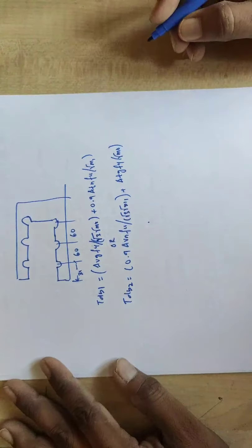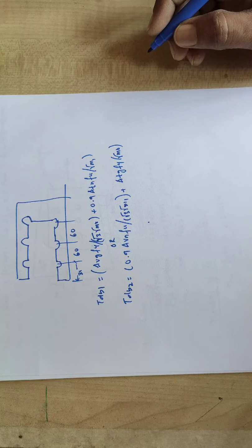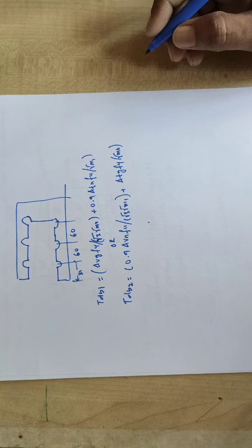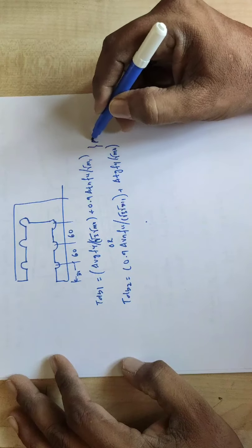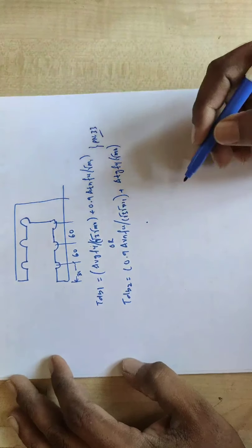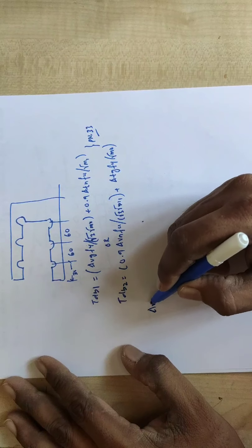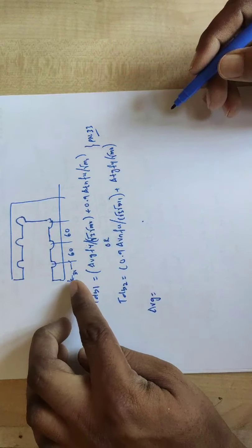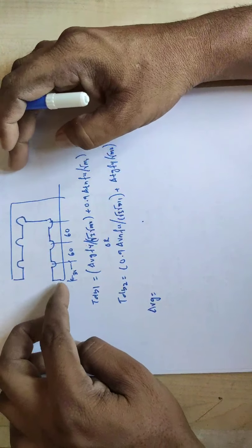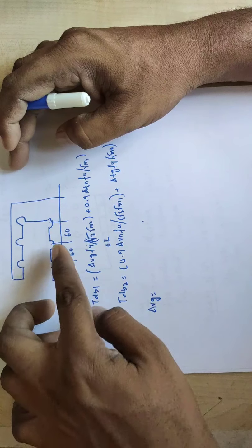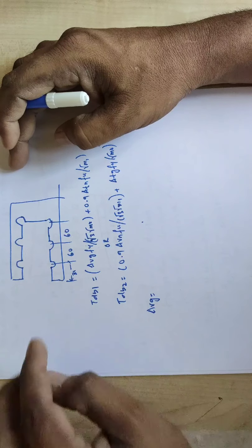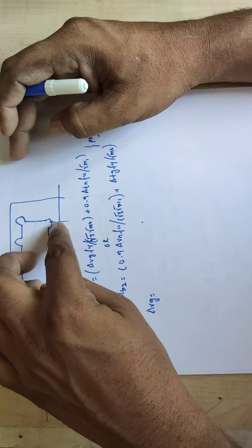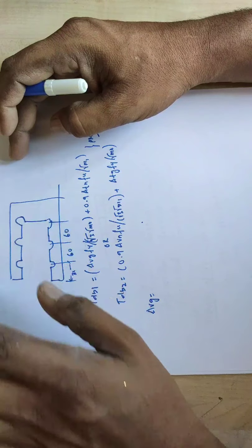Now we have to understand how to calculate these. First one is Avg. What is Avg? Avg, Avn, Atg, Atn: you can refer to the code book, page number 33, where you get the expressions in the theory. Now let me calculate Avg. Just see the diagram: 30 plus 60 plus 60. Block shear failure will occur on this side only, so I have to consider this area only.